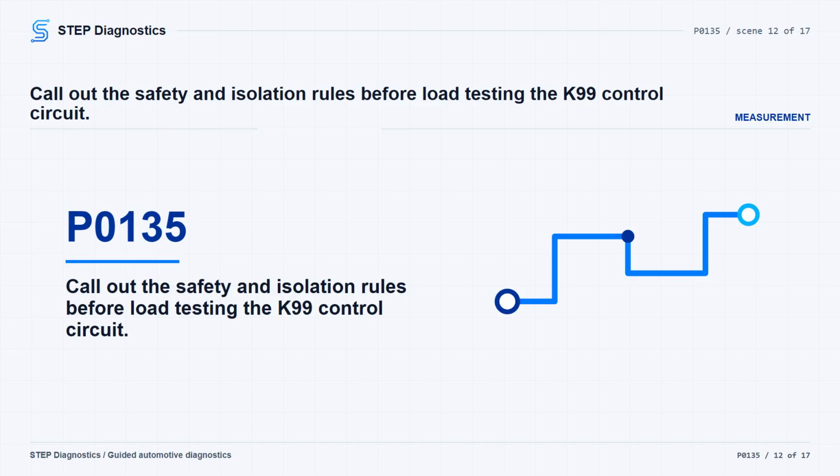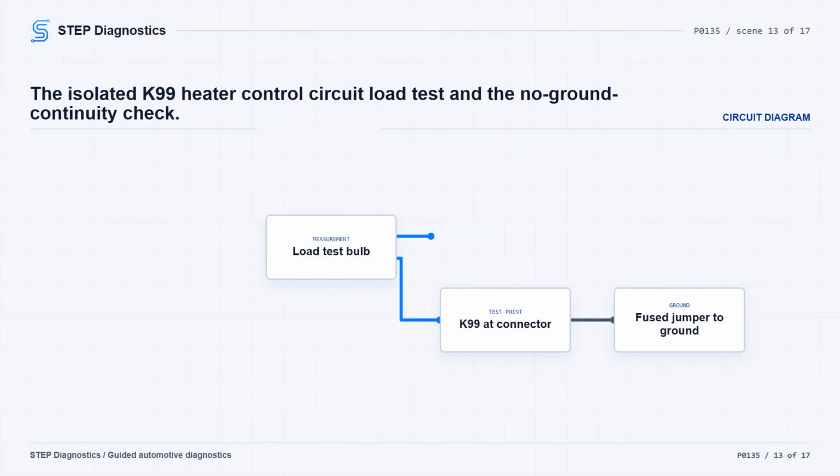The bulb should again be illuminated and bright, and there should be no continuity between ground and the circuit being tested. Use the same load tool logic here. A 3156 bulb has approximately 6.0 ohms of resistance when the bulb is powered and draws approximately 2.0 amps of current. A 12-volt test light can be substituted only if it draws enough current to effectively load test the circuit. Many high-impedance test lights draw very little amperage, less than 0.1 amps, and are not reliable to load test a circuit. The tool should draw more than approximately 0.75 amps.